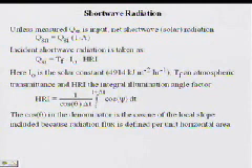If you've got a measurement of the incident shortwave radiation, QSI, then you need to calculate the net shortwave radiation by using the incident shortwave radiation times 1 minus the albedo to account for how much is reflected. If you don't have the incident shortwave radiation, you can calculate it based on the transmissivity of the atmosphere, the solar constant, and this quantity that I've called HRI, which is the sort of hourly radiation index.